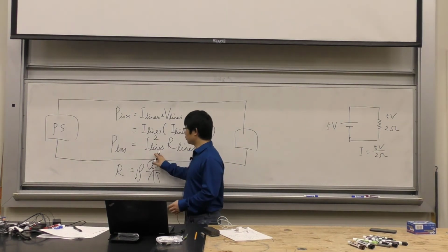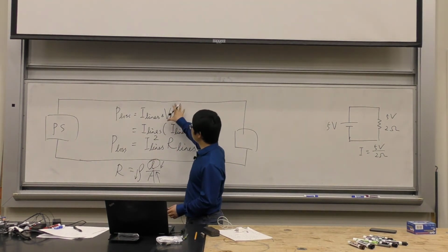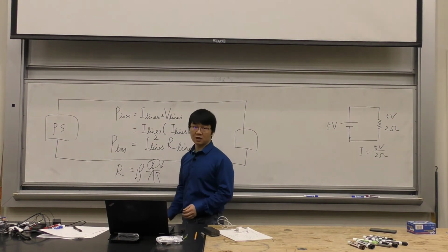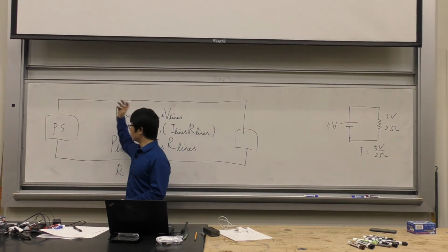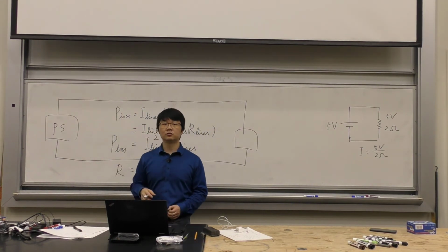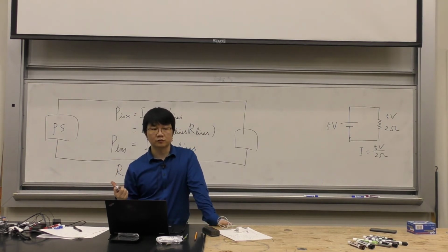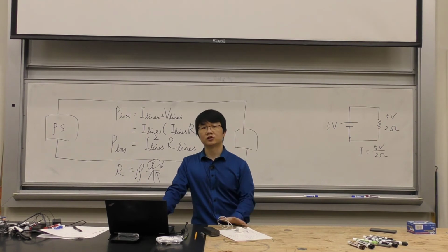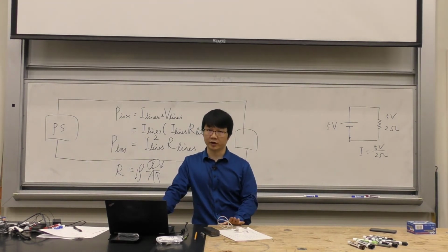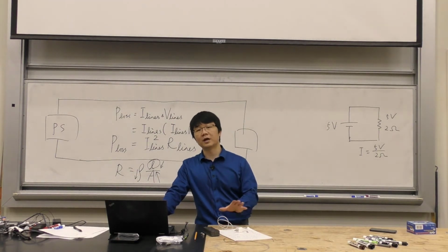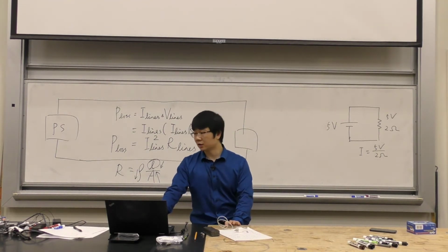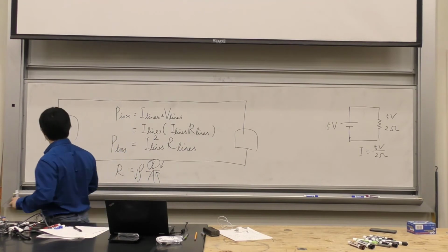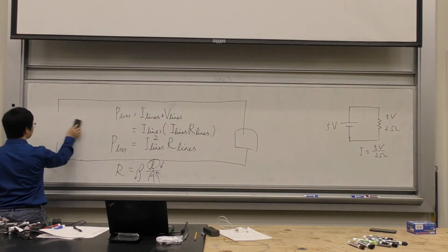So that's what we're doing in real life. I want to reduce the current on these transmission lines when the power comes out from the power station. How do I do that? Remember, we just discussed transformers. If you use a transformer, it can change the voltage for you. But at the same time, the current is going to change, right? So we can make use of that. So we can place a transformer, okay?